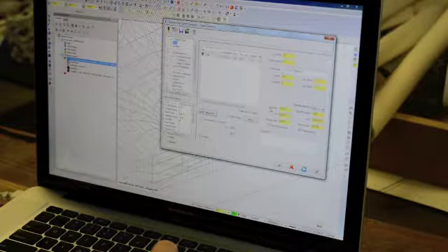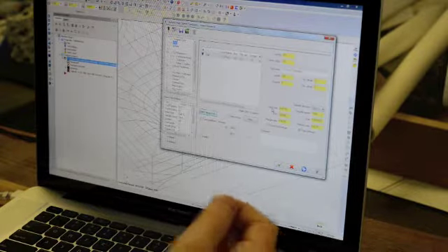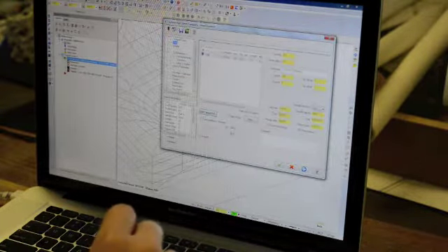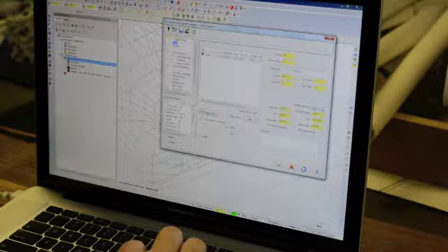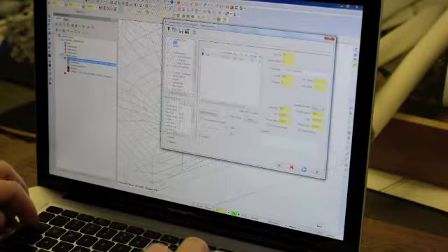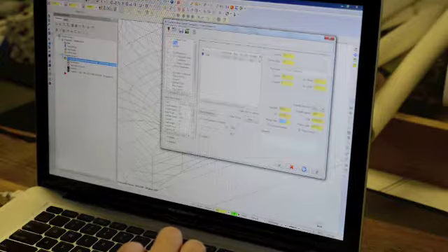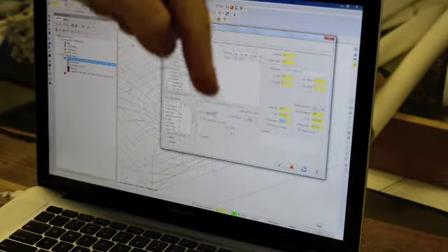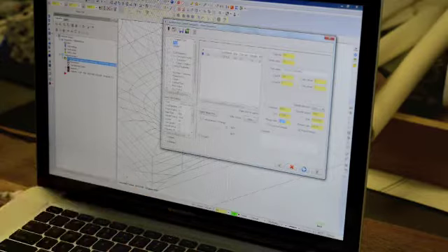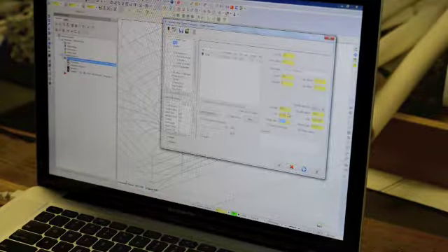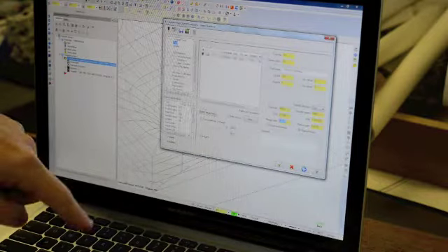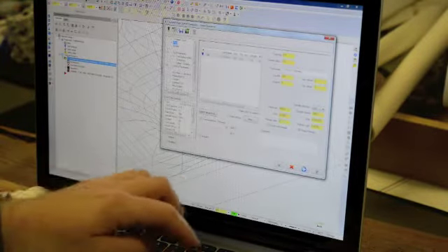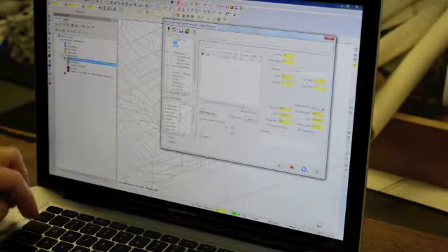So the feed rate, if you remember, that was the knob downstairs on the mill that we can control from 0 to actually 120%. What we've always done is set a maximum feed rate, which is 500 inches per minute. Then the plunge rate is how quickly the spindle will move into the material. It's a good idea to let that be a lot slower than the feed rate, which is how quickly the spindle is going to be moving through your material when it's actually cutting. I usually do a little less than half.